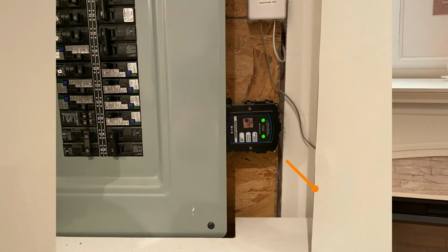In a lot of cases, and I know I have one of these on my panel, we have what are called surge suppressors. In a condition like that, where we have a power spike of electricity, the surge suppressor essentially grabs that and discharges it into the earth, so that the earth carries that discharge instead of it damaging the electrical equipment you have in your home. So that's another reason why we could see that grounded electrode becoming more alive with electricity.